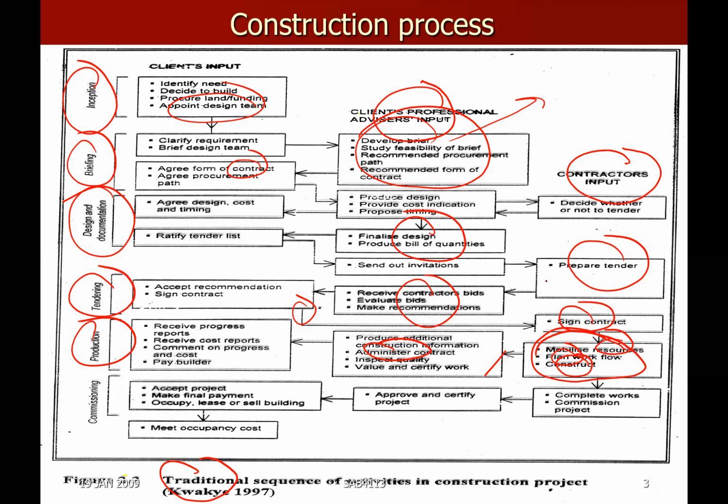And then the consultant has to monitor the contractor's work according to the quality and the quantity, and then certify the work, the claim by the contractor. The practice of the construction industry: you do the work, and at the end of the month, for instance, you submit the claim, what we call a progress claim, and then the consultant has to certify.